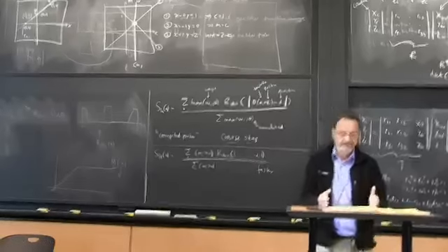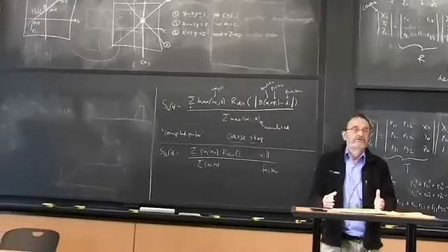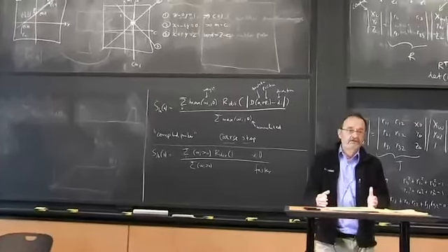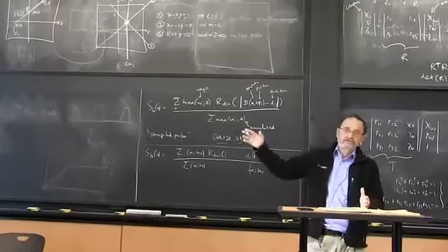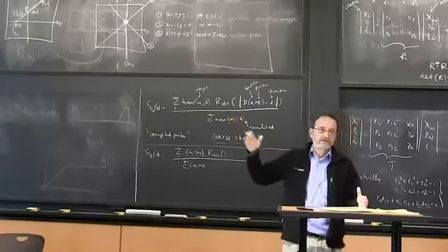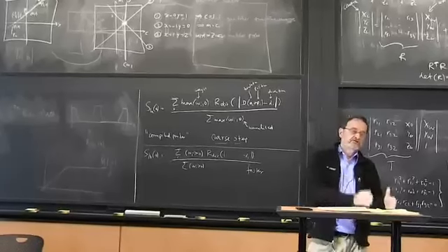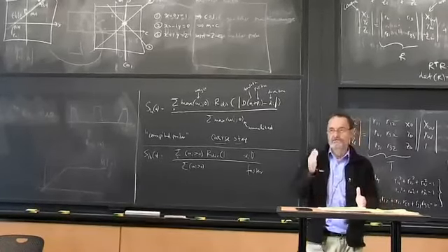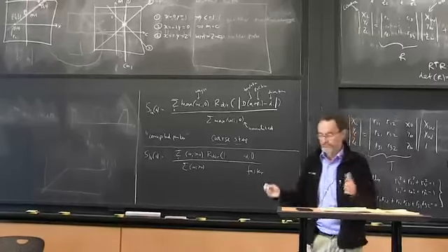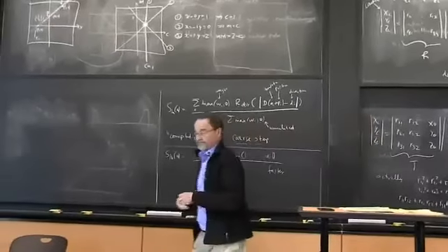So it's very important that your phone use a timing advance. In other words, that it knows my signal is going to take 5 microseconds to get to the tower, so I have to send it 5 microseconds before the appointed beginning of the time slot. Now actually, it's even worse than that because it doesn't know the time.